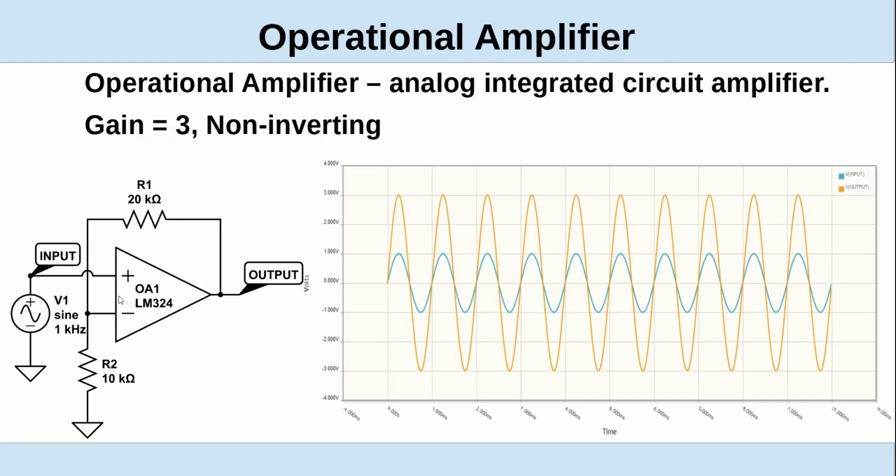So it takes essentially 0 volts between these two to generate an output. So if you use a feedback loop, and you have a voltage divider at this point, which will establish the gain. In this case, the 10 and the 2 is a third of the total value. So the gain would be 3.